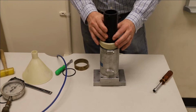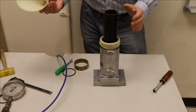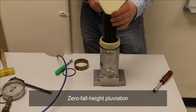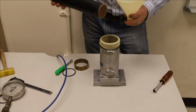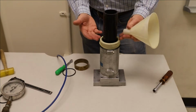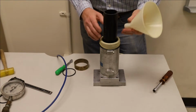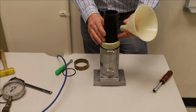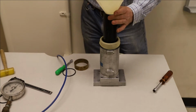So we're going to build the loose specimen first, and just like we did with the permeability testing, to build a loose sand specimen, we're going to use the zero fall height fluviation. So we have a cylinder with a screen at the bottom that the sand can pass through, and we put that screen all the way down to the bottom. So as we fill this cylinder up, doesn't really matter what density it's going to be. We're going to very gradually then let the soil flow through the screen at the bottom as we pull it up and deposit the soil with very low energy.